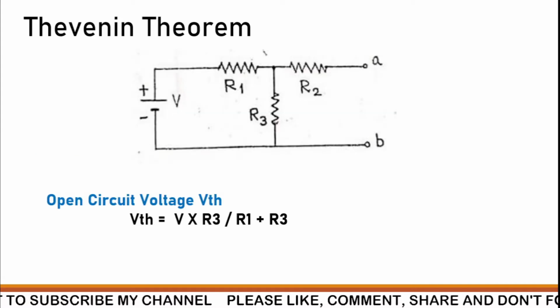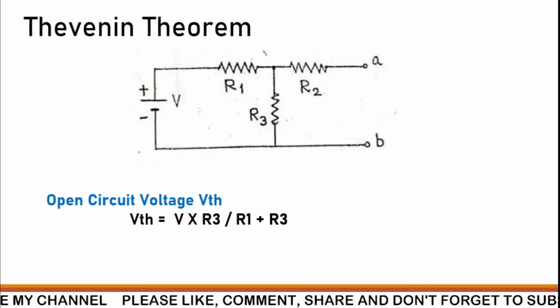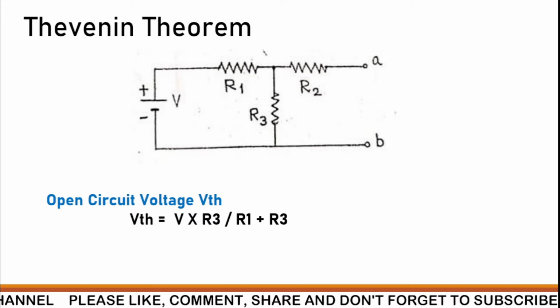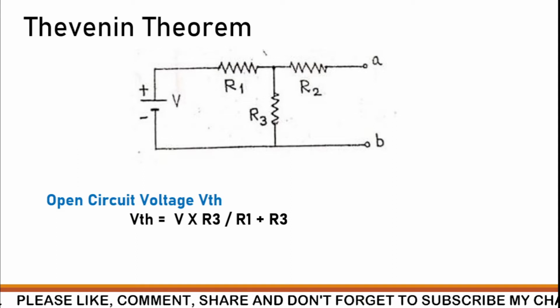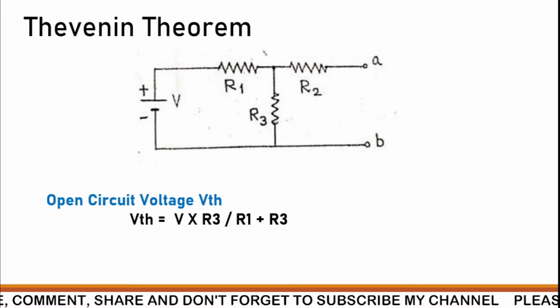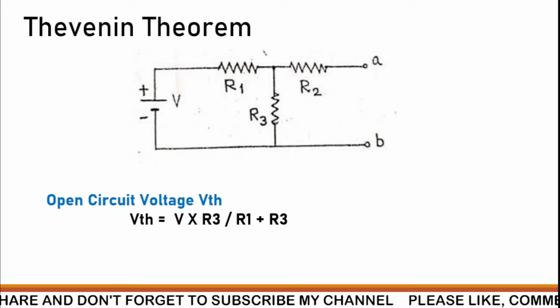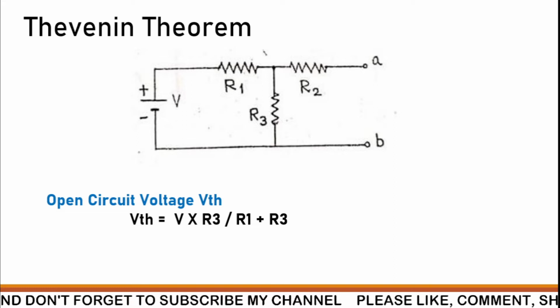As you know, the Thevenin theorem tells us that any two-terminal linear bilateral network containing different voltage sources, current sources and resistances can be reduced to a very short circuit, we can say a very small circuit. It contains only a single voltage source VTH and a single resistance RTH.